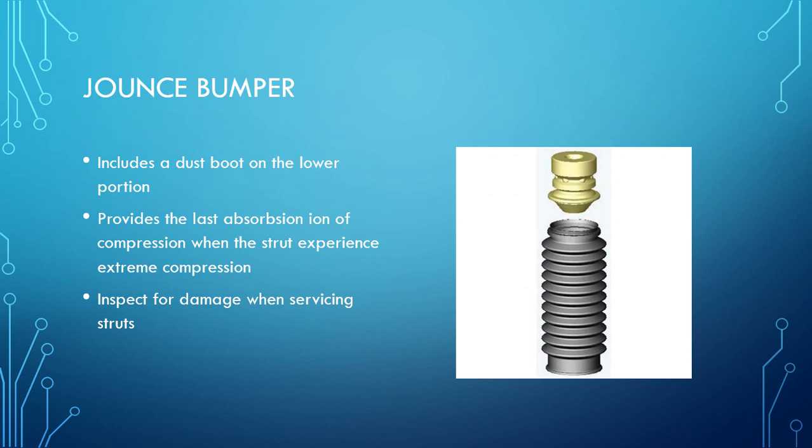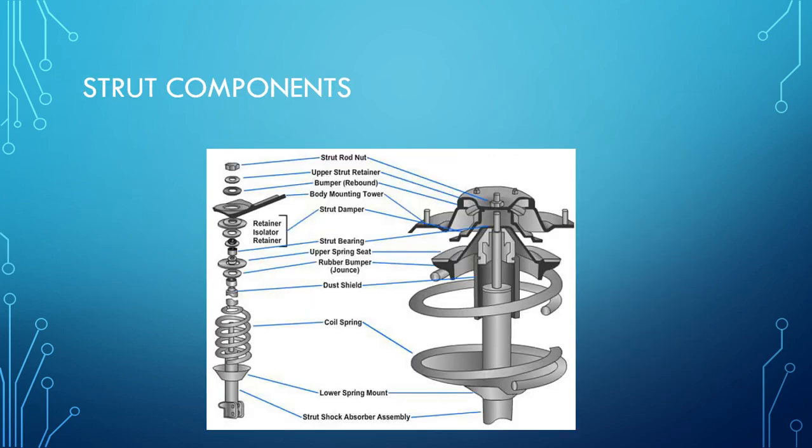Typically, what will happen is these cushions will elongate on the inside or deteriorate due to oil and/or a weak shock bouncing around on them. They'll physically just fall apart. So they can be purchased separately and they need to be replaced on service.